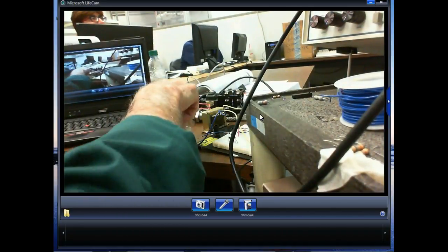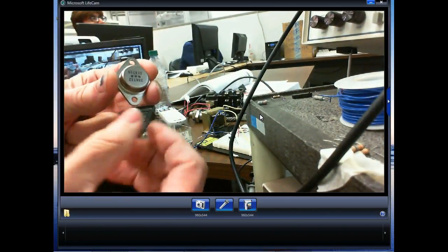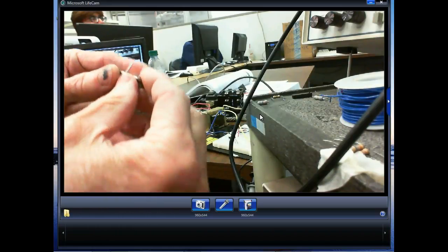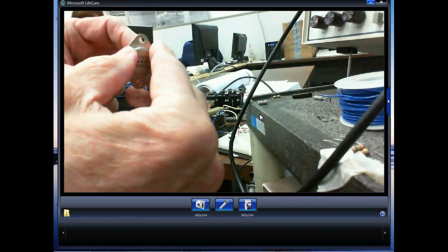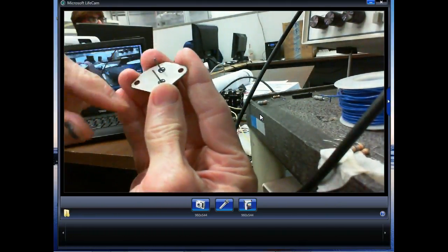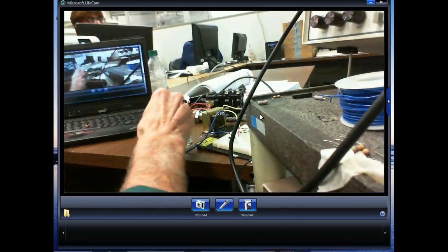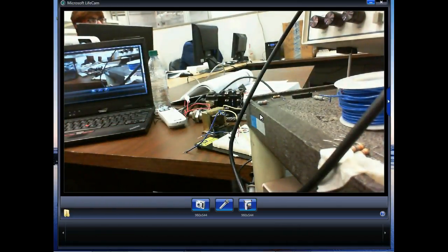And the biggest ones we have available is this guy right here. This is called a TO3 pack, and it's hard to see the 3 leads, but on this, the whole metal case is the collector. So this is the collector, and then these 2 leads right here, one of them would be the base and one would be the emitter. So whoever looks at them last, bring them back up here.